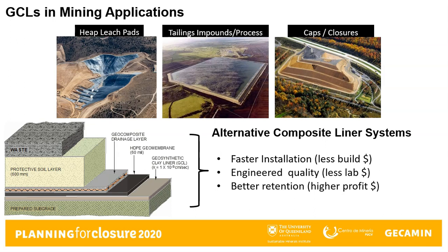Geosynthetic clay liners, also known as GCLs, have been successfully used for many years in various aspects of mining and ore processing applications. These applications include heap leach pads, tailings impoundments, and caps enclosures. GCLs are typically used as part of an alternate composite lining system.